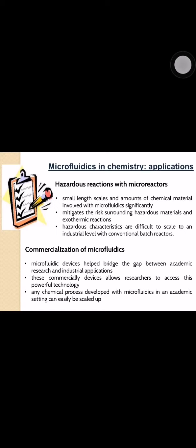The first one is hazardous reactions with microreactors. The relatively small length scales and amount of chemical materials involved with microfluidics significantly mitigate the risks surrounding hazardous materials and exothermic reactions. Reactions with these hazardous characteristics are difficult to scale to any industrial level with conventional bench reactors.